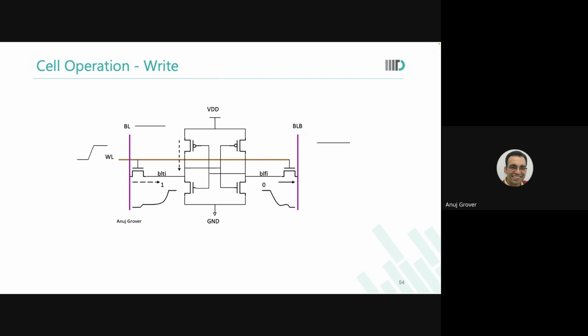In standard memories, what you are suggesting will take much longer to do. Not desirable. So we can just charge the bit lines. Like if we want to write something, if we want to write 0, then we will charge that bit line to 0.